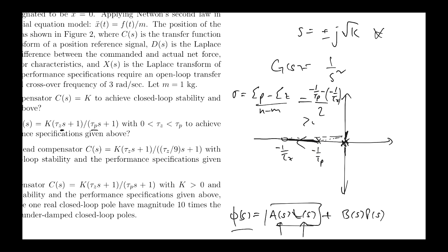But that will be a positive number, all right? Because look at the magnitude of minus 1 on tau z, which gets added here by virtue of the 2 minus signs, right? So this will be a positive number. So the asymptotes will be anchored at a point on the real axis in the right half plane, all right?